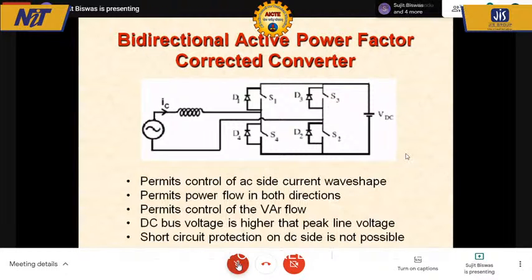Okay, one option might have been that I may like to put a small capacitor across the line in the case of an inverter. Then when I have an inverter, if I look from right to left, this is a PWM waveform. Then I have an L and a C filter. Then the voltage here should become nearly sinusoidal. Then the injection of harmonics into the supply should be very, very reduced. Yes, apparently it is so.